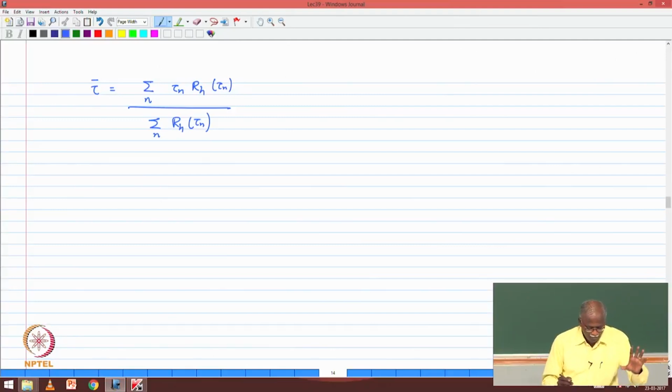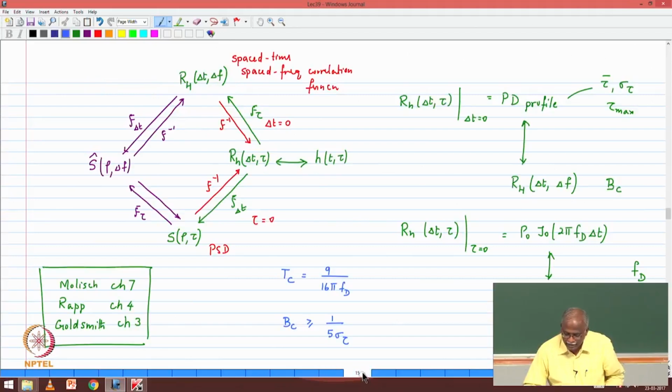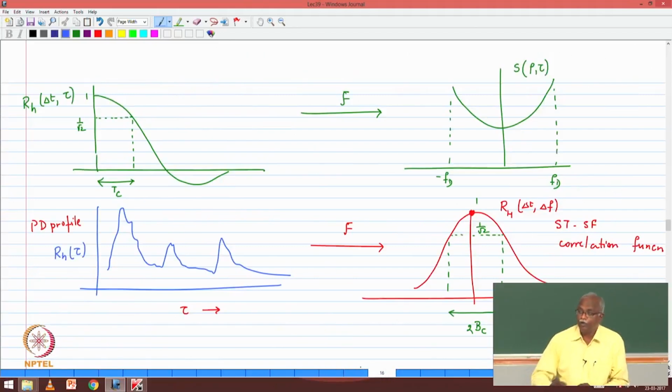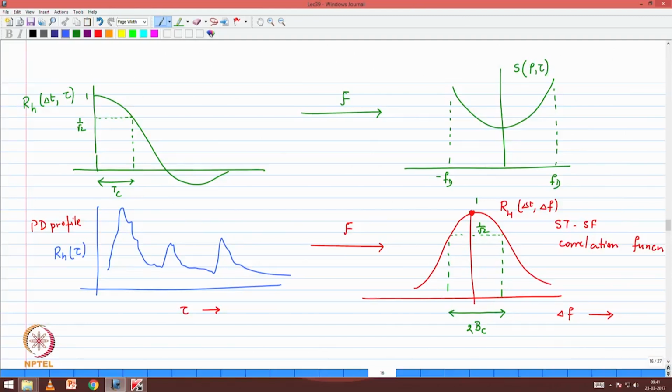So basically we have characterized the time variation and the dispersiveness of the channel in the two forms, which then leads us to the complete characterization of the channel. The time variation using the Bessel expressions relating to the power spectrum. The power delay profile, if I take the Fourier transform, gives me a correlation function which tells me how the correlation of the frequency response changes.